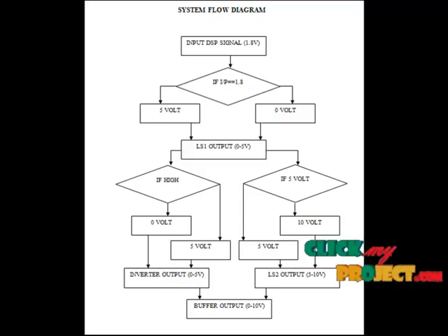Here, the architecture consists of a level shifter which converts the 1.8 Vpp signal generated by the external digital signal processor or field programmable gate array into triggering signals of 5 volt peak-to-peak pulses. Then the 5 volt signal is divided into two separate paths. The upper path contains a second level shifter and a tapered buffer to convert the signal to swing between 5 and 10 volts in order to drive the gate of the PMOS transistor of the output driver, because the output driver consists of a high voltage transmitter.